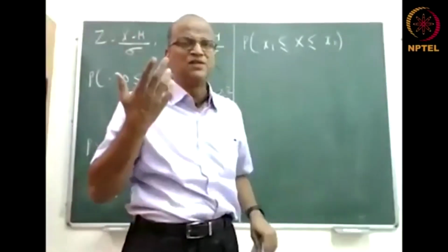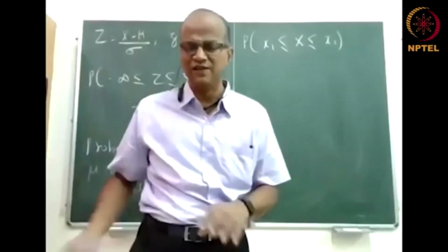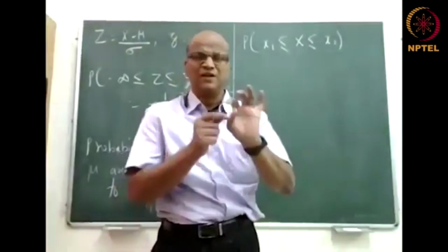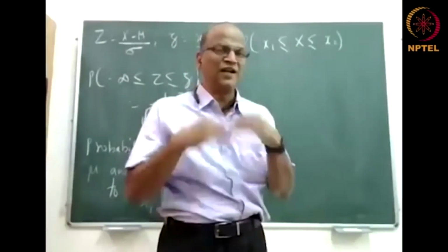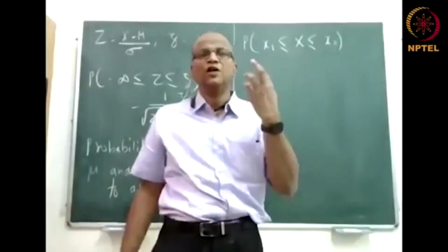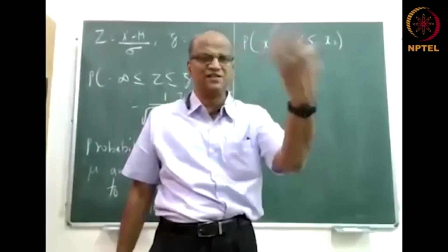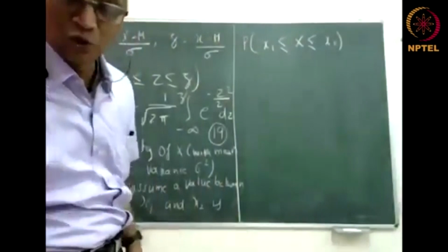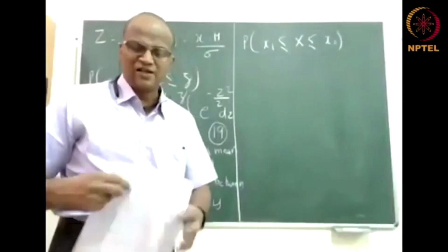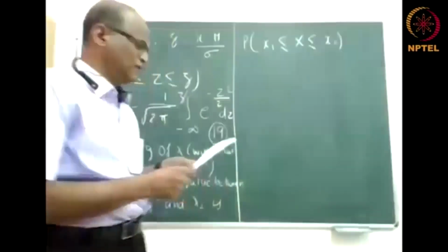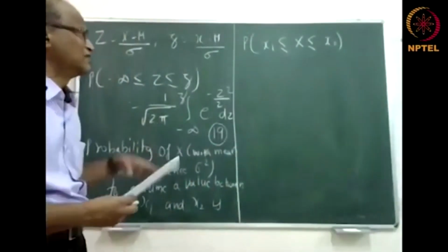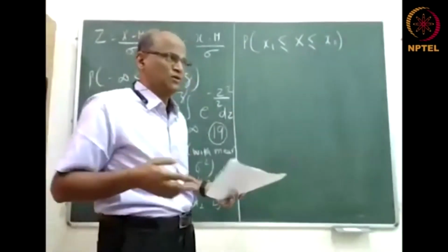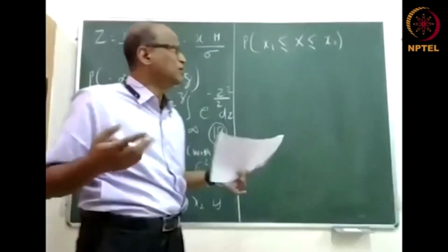Why do you want to do that? 100% inspection of a nut and bolt. Some Sundaram Fasteners, TVS Fasteners will make hundreds and thousands of nuts and bolts every day. It is not possible for them to fully test the dimension tolerance and check everything. So they will take a sample, and they have to use a lot of statistical principles to figure out that with a certain amount of confidence they can say that this is the quality which we will give to the customer. Statistical quality control, total quality control is fine, but is it worth doing all this for millions of nuts and bolts? That's what you want to figure out. So you can use statistical principles intelligently to reduce your labor. At the same time, you can predict something with reasonable confidence.